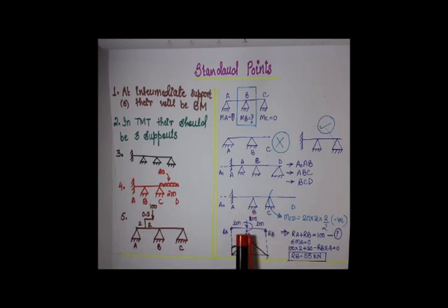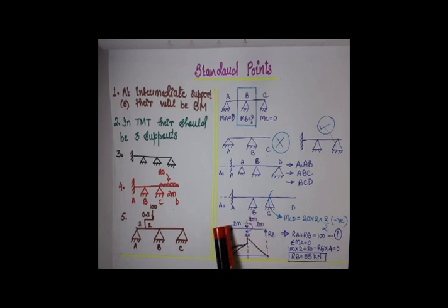Since it is going clockwise, that is we need to see it from the point A, it would be moving clockwise. If we are standing at the point load of 100 and need to go to point A, it is going clockwise, so of course it would be positive. So 100 into 2. Now plus 20, because it is already given as 100 into 0.2, so plus 20, again in the clockwise direction, therefore positive.